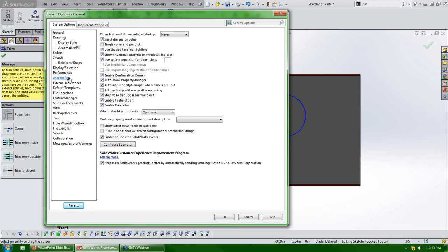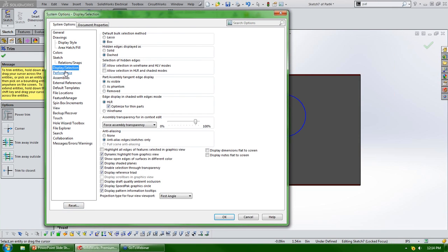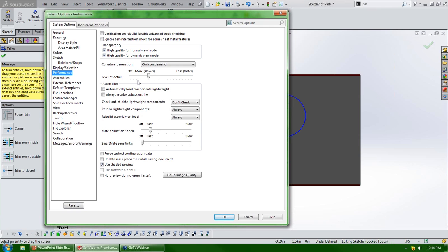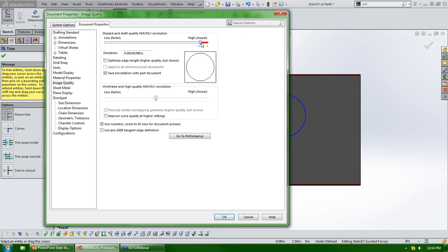All right, what else do we have under options here? For performance, there's actually two key options in here that will help you speed up your time spent in SOLIDWORKS. The first is your level of detail. If you reduce this down to less detail, which is going to be your reflection on the floor, your static effects inside the model, you'll be able to create and update your models much quicker. Similarly, for your image quality, if you're teetering along this red line, SOLIDWORKS will even give you the warning that your file size is going to increase the more precise your image quality is.